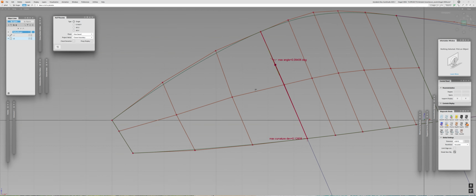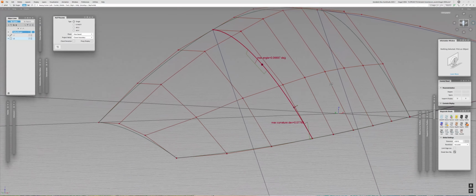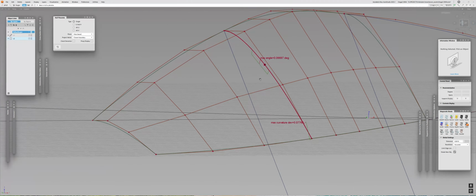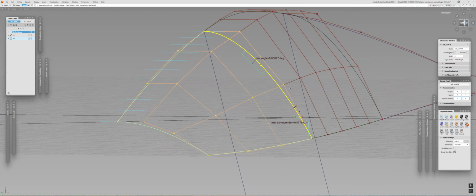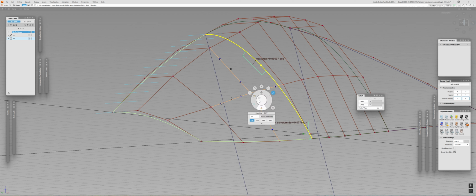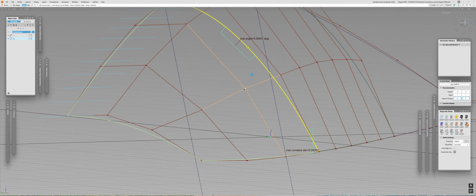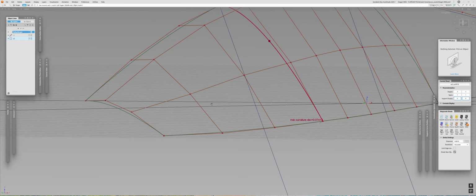Now, first of all, what I'll probably do is planarize my holes using the closest boundary, like that, and it already significantly helps me. Now let's work with the tangency issue. So I'll pick this CV, go to direct modification of a CV, and move it along the normals just a little bit. Okay, and now we have this.